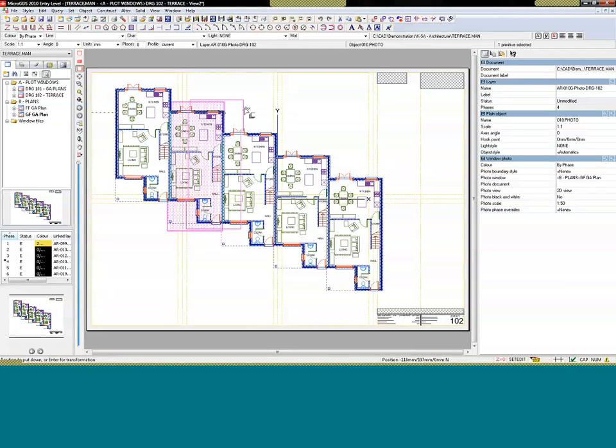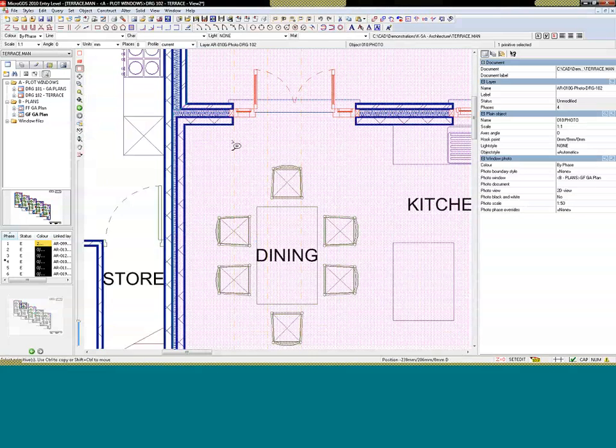They're similar to a viewport, but you'll see that they're a peculiar shape. And the reason they're a peculiar shape, to just undo that, is so that when we zoom into our corner here, you can see that while the original drawing was an external wall, by adjusting the shape of our overlap, we've actually created a proper internal wall junction.